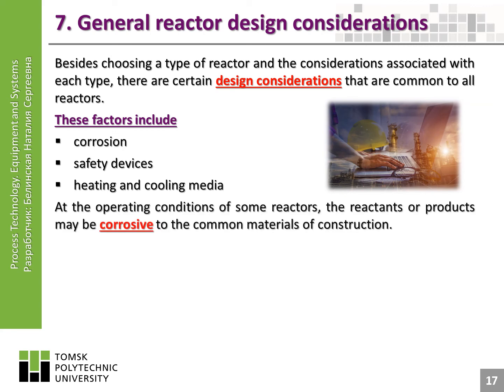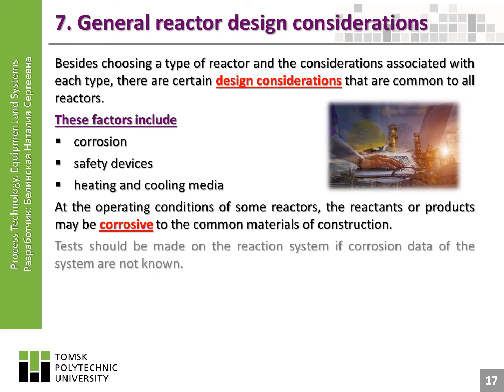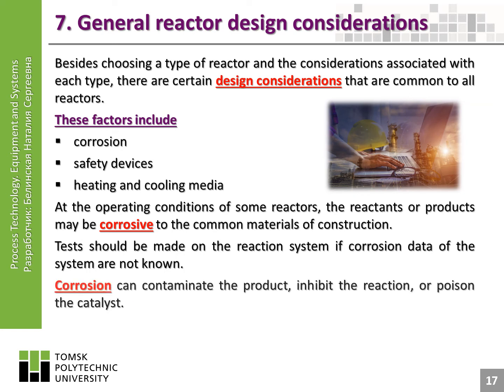At the operating conditions of some reactors, the reactants or products may be corrosive to the common materials of construction. Tests should be made on the reaction system if corrosion data of the system are not known. Corrosion can contaminate the product, inhibit the reaction, or poison the catalyst.